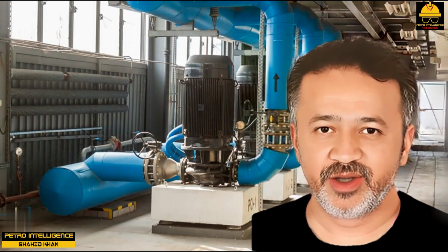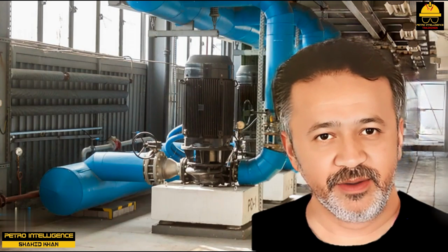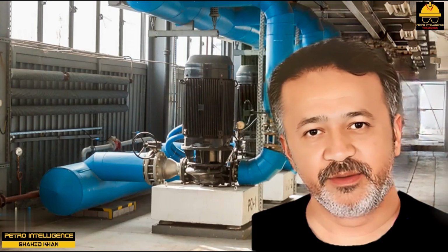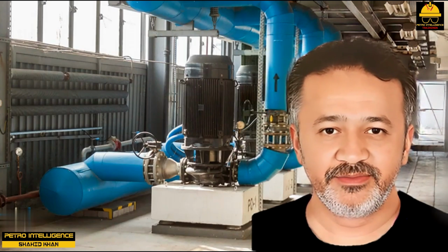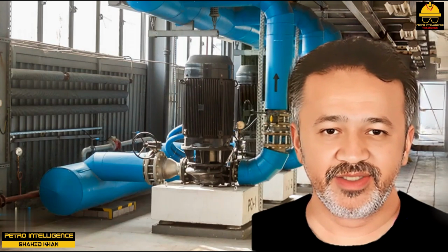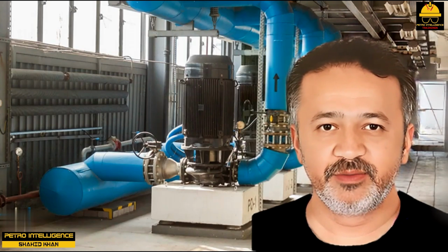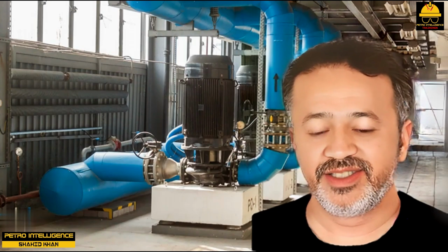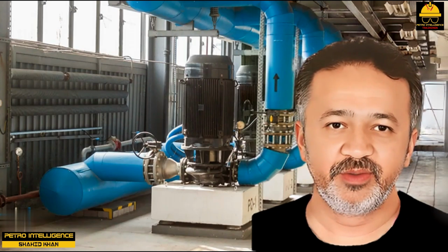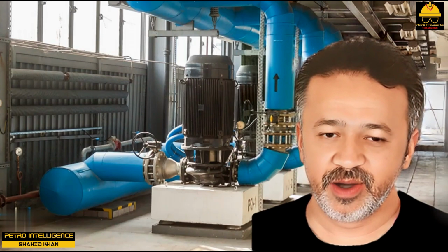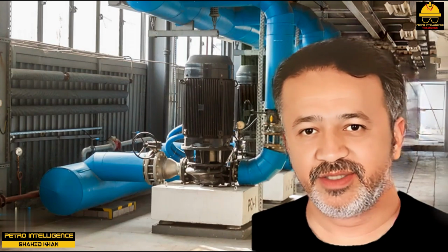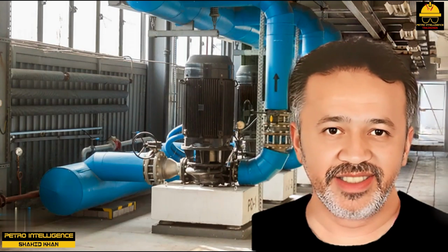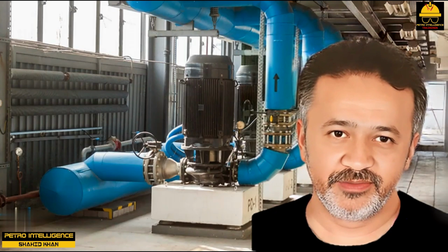As a rough rule of thumb, reducing a pump's impeller diameter by 10% will reduce the amp load by 25%. Not only will this save electricity, but the motor will run much cooler. Unloading the motor by 25% may increase the life of the motor windings by 10 years. When the control valve downstream of a pump is operating in a mostly closed position, the pump is a good candidate to have its impeller trimmed.